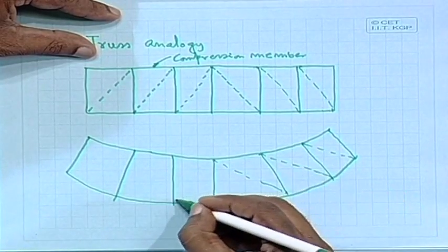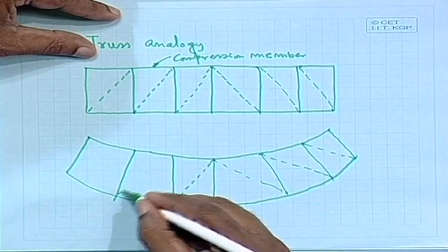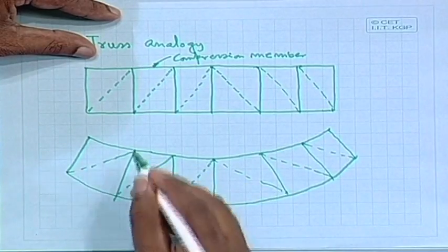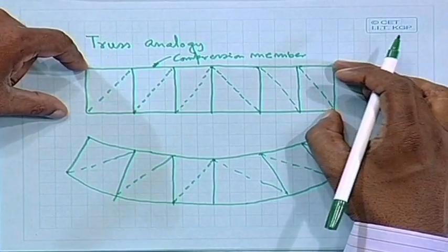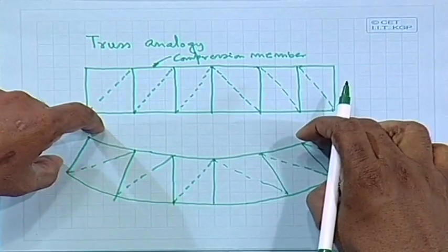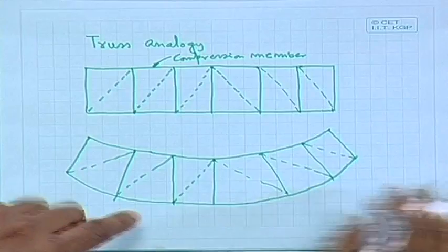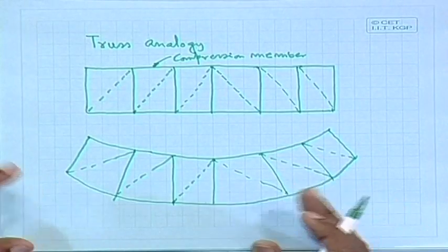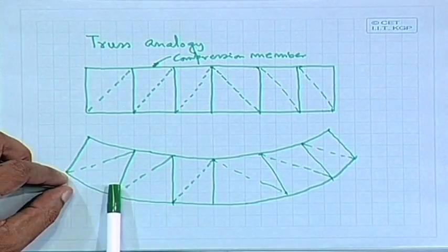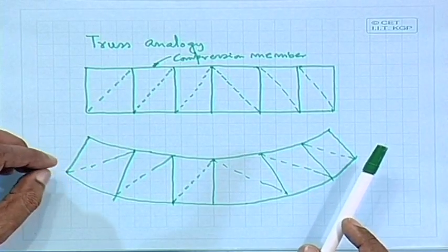You can find out from the deformation, that means as if it is like this. So, this truss is deformed in this fashion. What you can find out, the members which are extended, from here you can say qualitatively which members are tensile and which members are compression. You can find out from this deformation diagram, the members which are extended will obviously be tensile members, and the members which are shortened will be compression members.